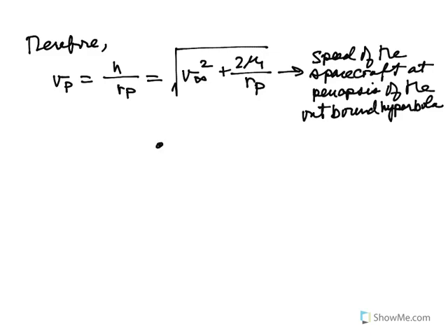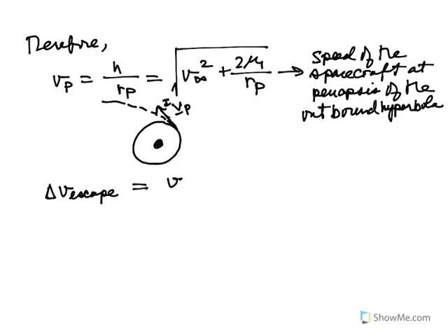So if we say here's planet 1, and here's the orbit, and here's that outbound hyperbola, which I drew before, this velocity is tangent to the orbit. So this is the periapsis velocity. And the speed corresponding to it is going to be such that when I apply a delta v, which is now the escape delta v, it is going to equal v plus minus v minus,